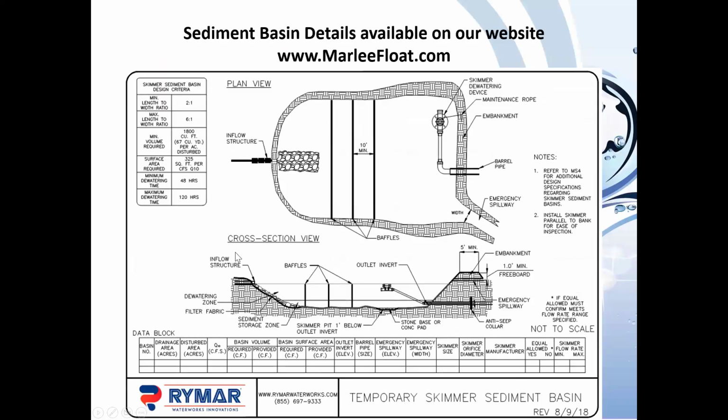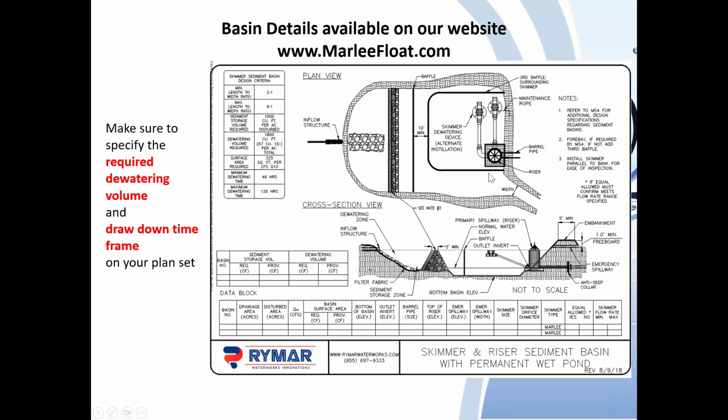We have sediment basin details on the site as well. We actually have 4 different details. So this one would be a temporary basin, so it doesn't have an outlet structure, just has a pipe through the dam and would be dry. This would be more of a typical riser structure, possibly a permanent basin. And this one would be wet, so we'd have that permanent pool.